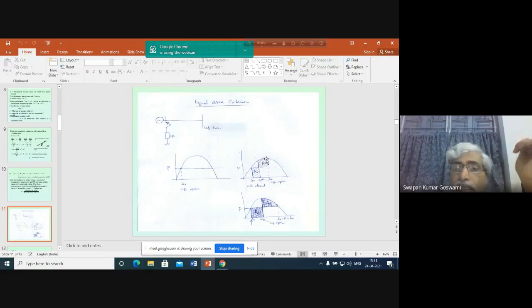As delta is increasing, you see that we can find an area A2 here, which basically represents the energy that has been extracted from the generator. Why has this been extracted from the generator? Because the generator rotor is actually losing speed. Its speed is being decreased. As a result, kinetic energy is released by the generator. This kinetic energy is actually being used to supply the power output.